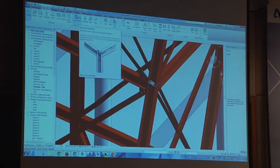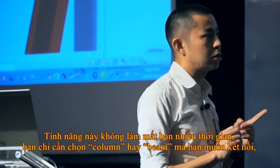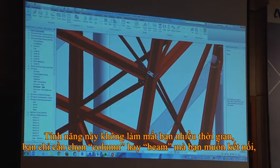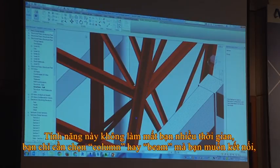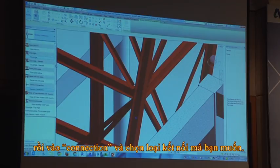Okay, still remember just now I was talking about the industry starting to move into prefab construction, prefabrication construction, and also modular construction. This is part of the tools that helps them move projects to prefab and modular construction. For example, this kind of quality of steel connection doesn't take you much time. All you need to do is select the columns or beams that you want to connect, and then go to the connections over here.